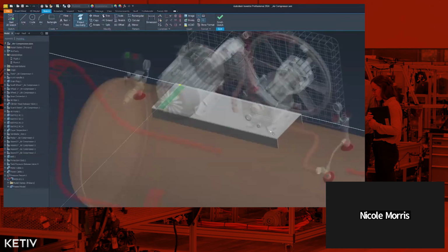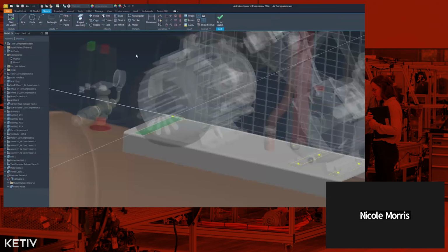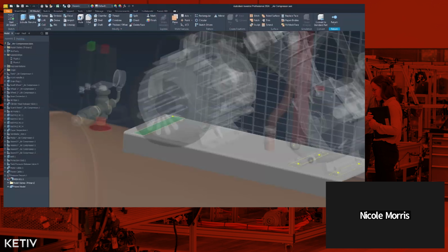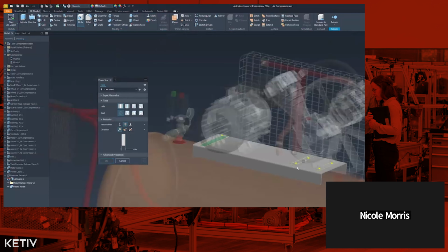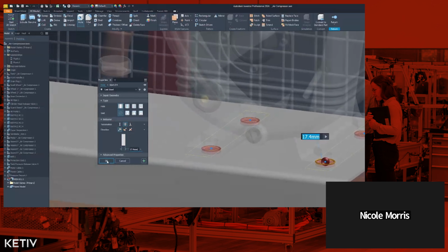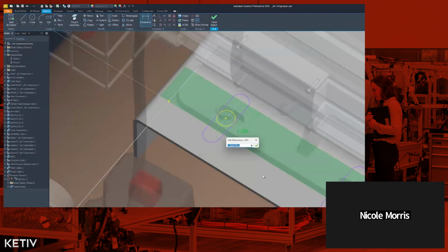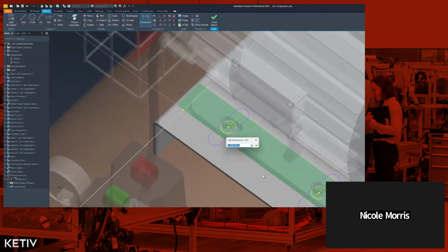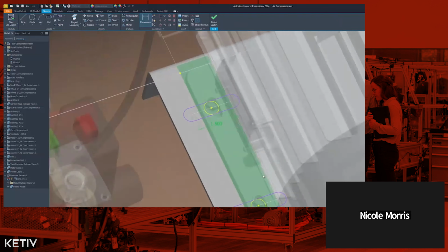So next Mario considers where his holes will be placed for the pump and motor. He does not utilize bolted connection like Nicole. On the pump side, he creates a sketch on the surface of the bracket, projecting the hole geometry and adding the holes at the part level.